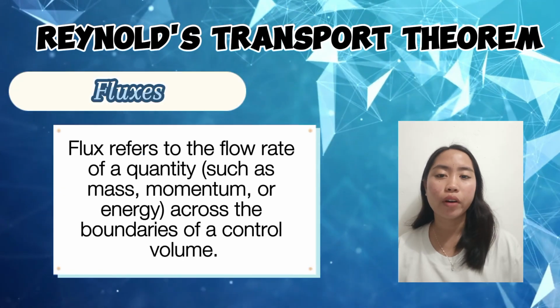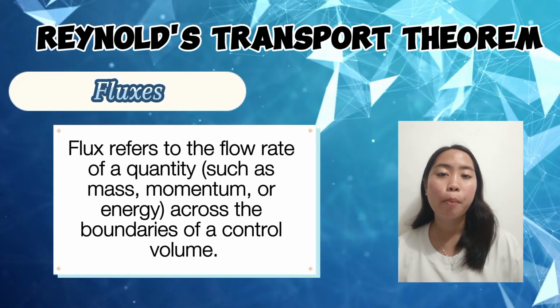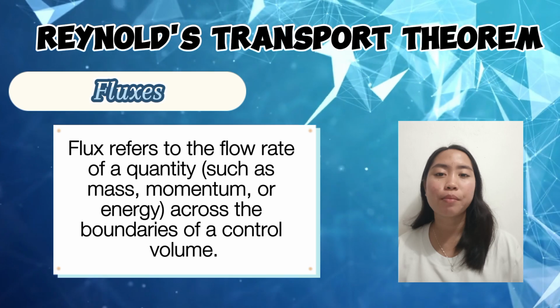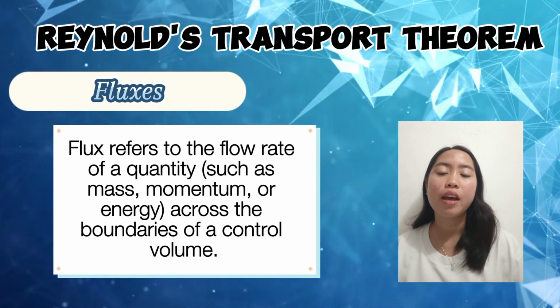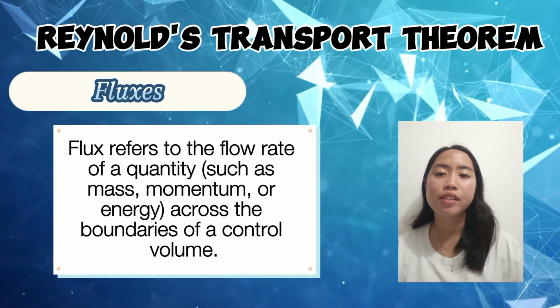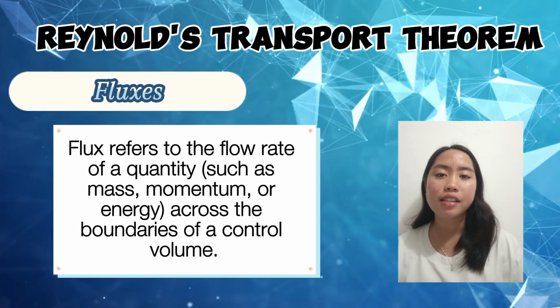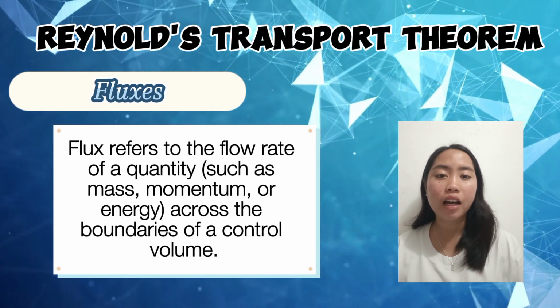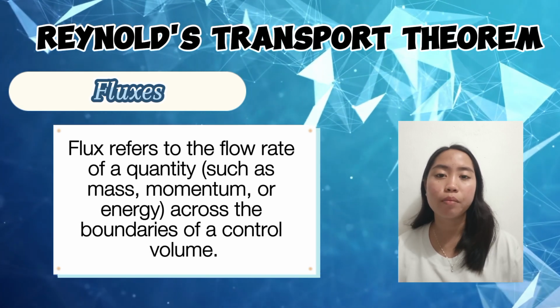Flux refers to the flow rate of a quantity such as mass, momentum, or energy across the boundaries of a control volume, meaning fluxes are integral components in Reynolds transport theorem as they account for the movement of a quantity across the boundaries of a control volume.